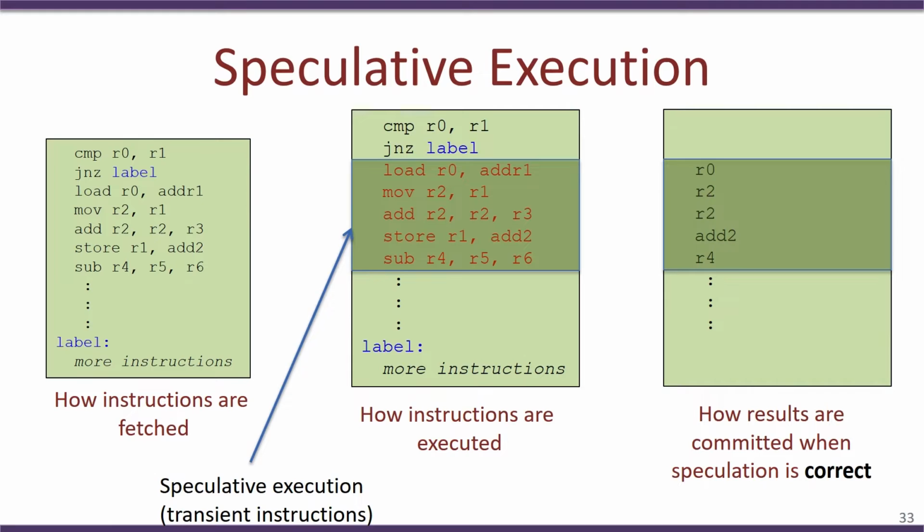Now, advanced or very popular recent microprocessors have a considerably large pipeline, and as a result there may be several hundred or so instructions present in the pipeline. So every time there is a branch like this to another memory location, this entire pipeline would get flushed, and new instructions would need to be fetched from the target memory. So this could cause quite a considerable performance overhead.